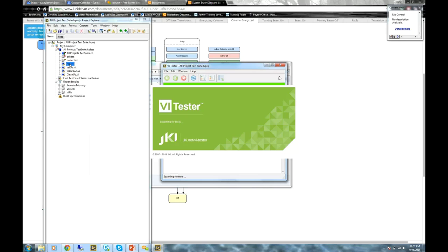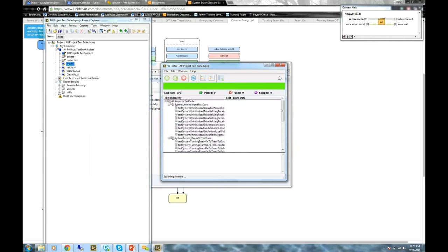So you could have something in your test suite where you want to do some sort of preparation, some sort of step ahead of time, and maybe you want to vary it by test case. You can create a new VI from dynamic dispatch template, or a new dynamic dispatch VI, and then you can override it in each case.